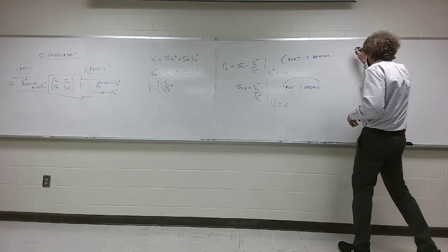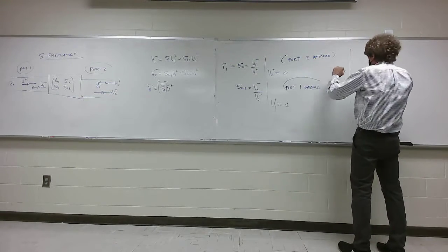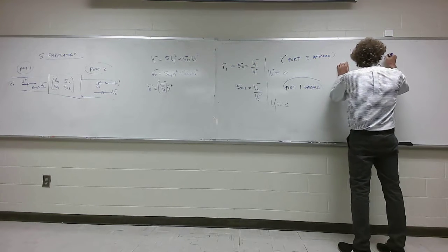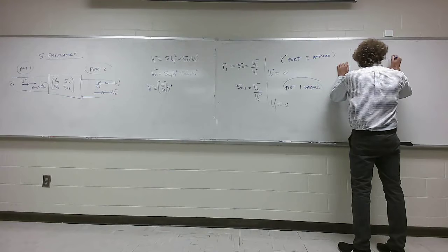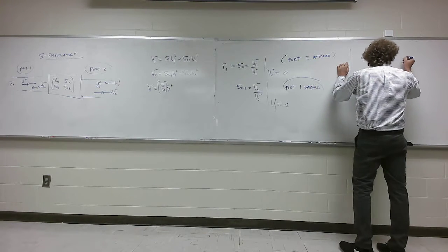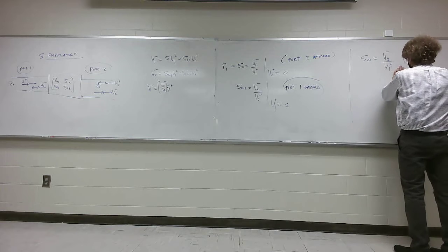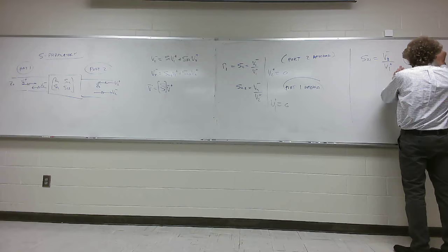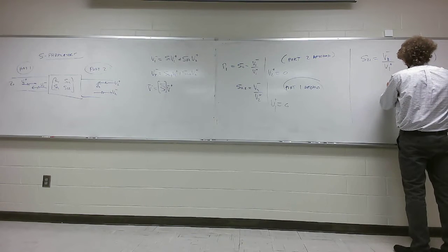So when we talk about voltage gain with S parameters, S21 is equal to V2 minus over V1 plus, and this is assuming that V2 plus is 0, and this is called the forward voltage gain.